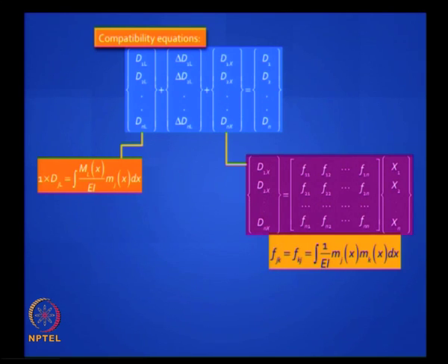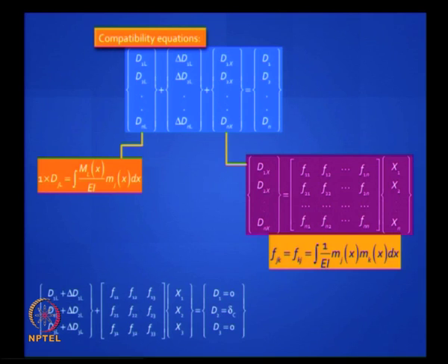I am writing all the expressions, and in this particular problem where I have only 3 unknowns, I can write that equation, then I can solve for x1, x2, x3 by inverting that flexibility matrix or using some elimination method and then solving it. Once I have the solution for x, I have got the correct force response, I can draw my bending moment and shear force diagrams on my overall free body. Is it clear? This is a broad method, we have done this.